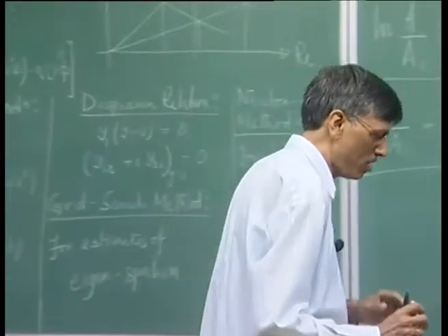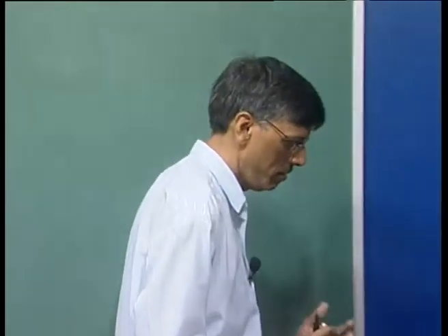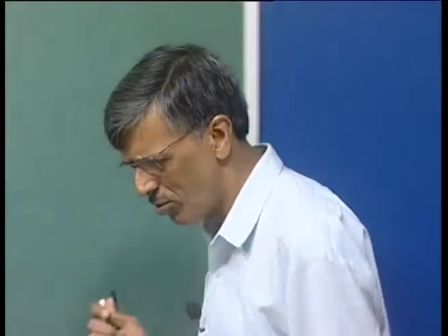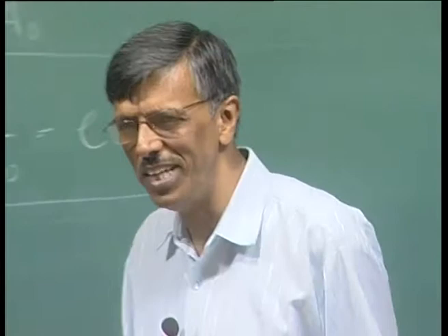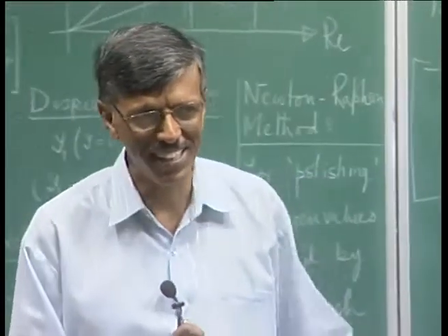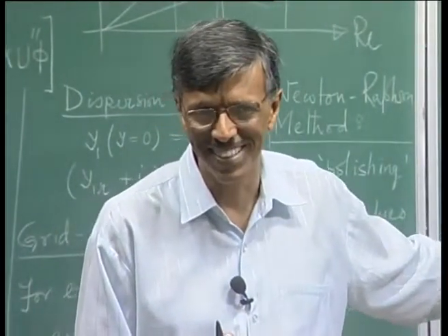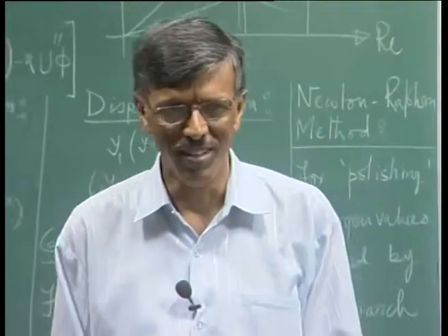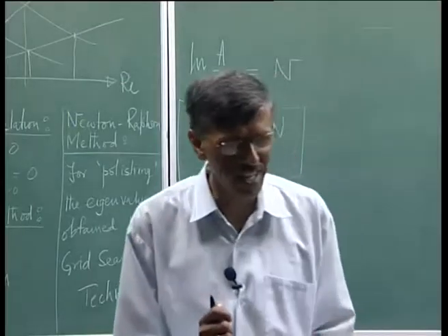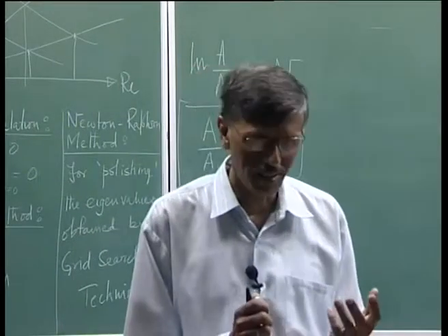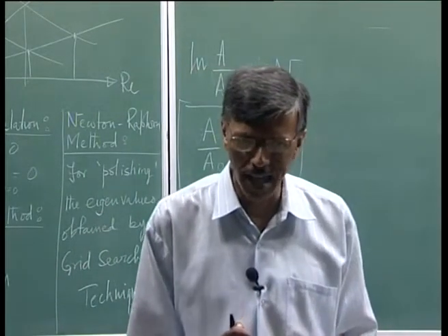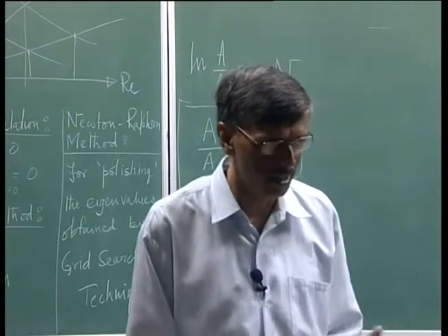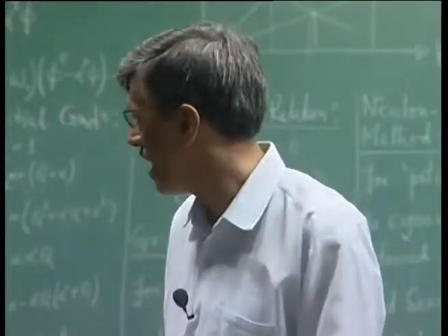So, please do not get too carried away, because you would be coming across various claims where people would say, oh, we use a very sophisticated theory called the e to the power n method. This is not theory. This is of course theory in the sense that you have idealized the actual flow in terms of a locally parallel flow, and you have obtained all of that.